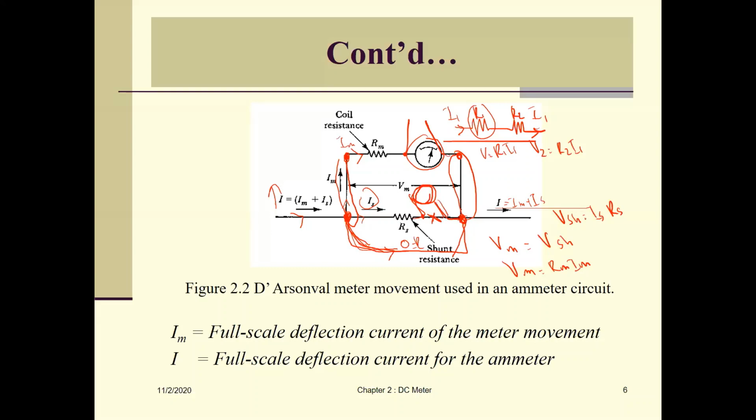If you want to measure the voltage, you put it in parallel. For example, we want to measure the voltage here, Vm. You can take your digital multimeter or voltmeter and put one point here and another point here. To measure the voltage, we tap in parallel. For parallel, the voltage will be the same. For example, Vm and Vs are the same.